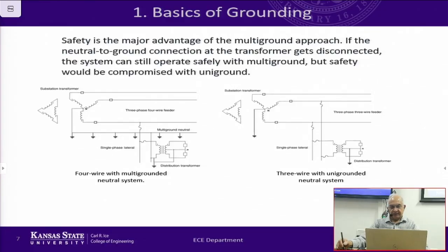And this is where you see that the secondary is split into two parts. It is 240 volts, but half of it is 120, other half is 120. And the midpoint is tapped and connected to ground. This is a very important thing because the ground has to be common throughout the system. You cannot have one part grounded in one place and another part in another place. It's a continuous ground that runs all over the place.